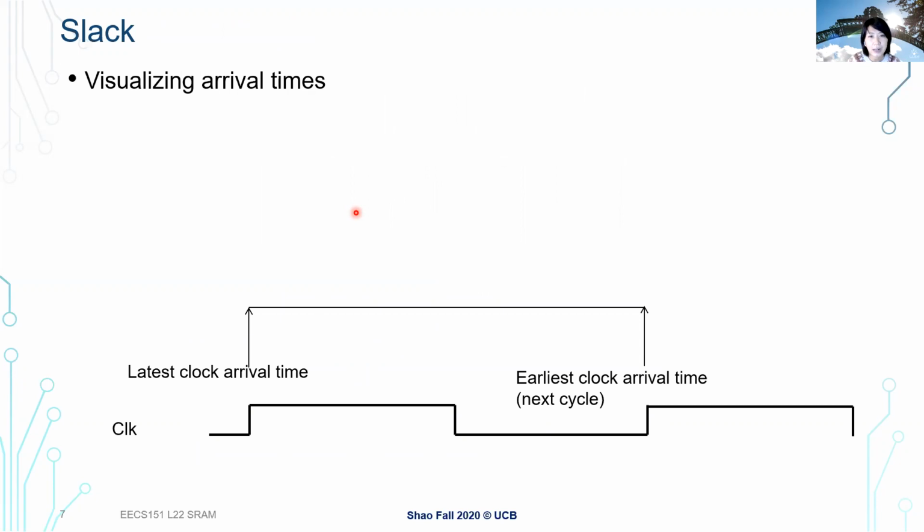So if we recap the different events happening in each individual clock cycle, which is the time between two rising edges of clock: the hold time concerns the input and clock pair, and specifies how long the input needs to be stable after the rising edge, after the clock transition. We need to make sure the data is stable for the hold time constraint before this data is overwritten.